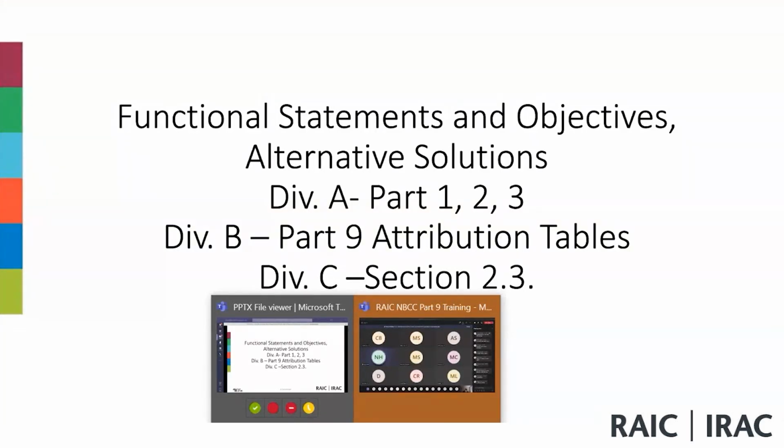So in 9.10.8, fire resistance and combustibility in relation to occupancy, height, and supported elements, this is all types of construction. So you can use both combustible and non-combustible construction.